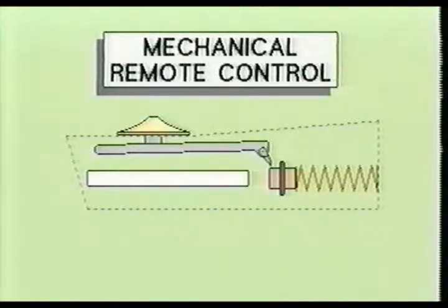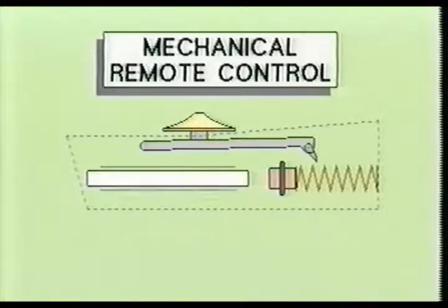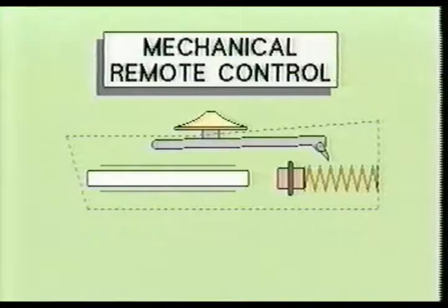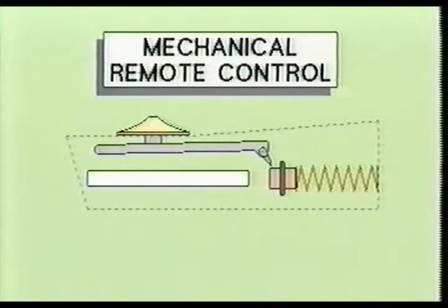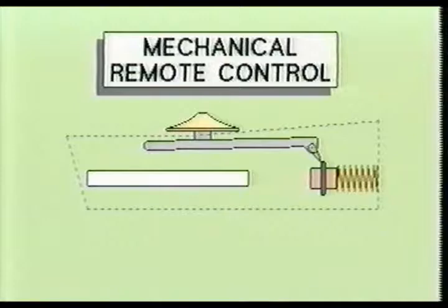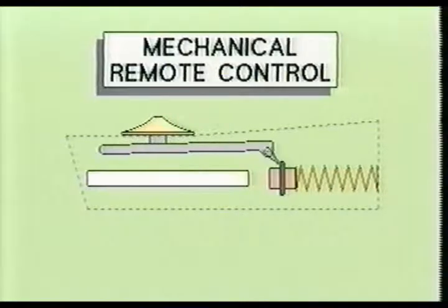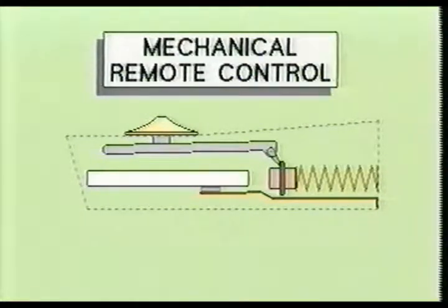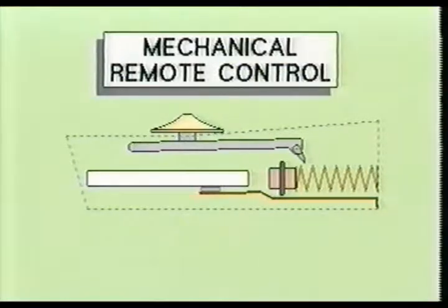The control unit works by the user depressing one of the function buttons, which creates tension on the spring. When the button comes to the end of its travel, the spring will be released and recoil, allowing a small hammer to strike the end of the aluminum rod. The aluminum rod thus generates a specific ultrasonic frequency, which the television receiver recognizes as a function signal. After a predetermined time has passed since the function button came to the end of its travel, a silencer is sometimes used in the remote control device to end the vibrational ringing of the aluminum rod.